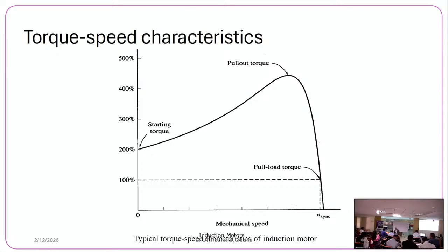So core loss we are telling, when we say core loss we mean stator core and rotor core loss. But in the yoke, some flux reversal is occurring, cycling. There will be some yoke loss in the yoke, but we don't consider it in core loss. It is in stray load loss. The yoke is the physical support of the motor. In a transformer, the same loss is there in the transformer tank. The tank will also cause some loss. That is stray loss in a transformer.